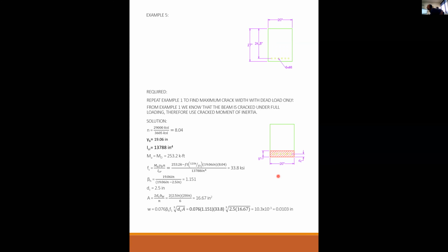Okay. So it's better to use more smaller steel bars to control the cracks than bigger bars, but fewer. Yes. Within reason. 6 number 8s is a good answer. That's totally buildable. You can even go, instead of 6 number 8s, 5 number 9s.